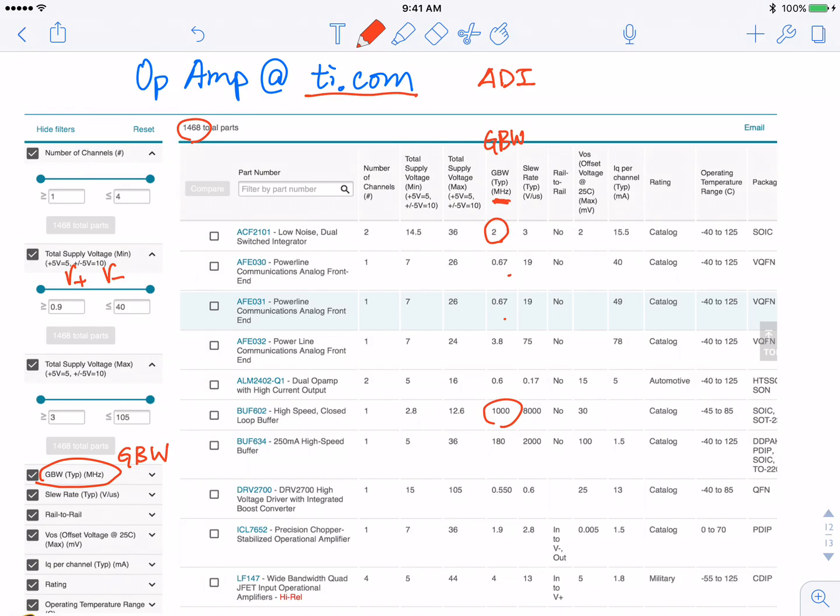This can only give you so much. If you want to work with a full bandwidth of 2 megahertz, you run out of gain. Then you go to this one with a higher gain bandwidth product. They don't come for free. If you keep checking the spec down the same row, you will see where you take a penalty. Maybe the power consumption is much higher. Usually it's not price. These two are all on the order of $1 per unit, really cheap, so it's usually not the price. But you may pay a penalty in power consumption, okay?